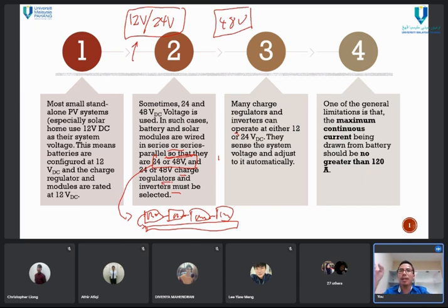So this is normal lah. Usually it is very rare for them to have a module with only 24 volt. Usually they come with two sets, 12 and 24. They can support both. But please make sure before you buy it, you need to check the rating. I'm afraid there are also inverters that only support 24 volt. Charge controllers and inverters that only support 24 volt mean that if you have 12 volt, it doesn't work. Please check it properly.